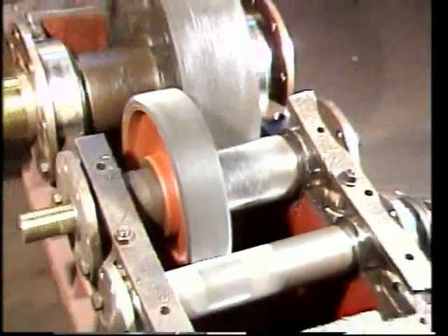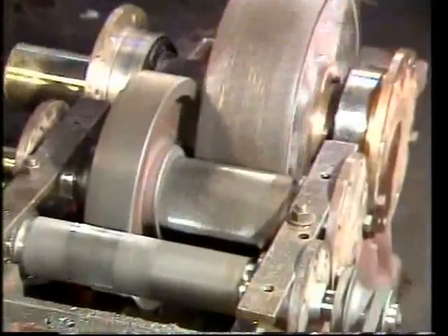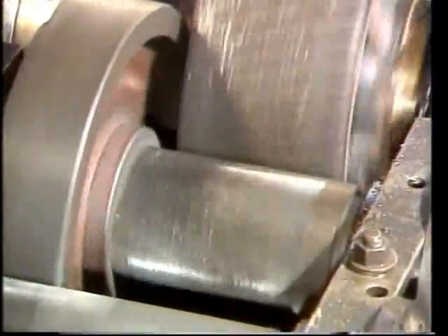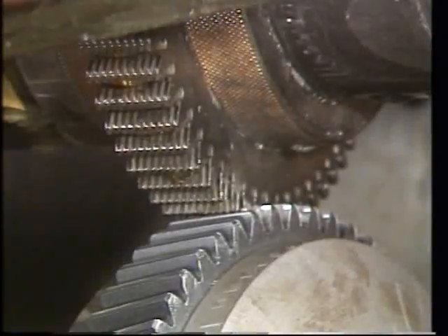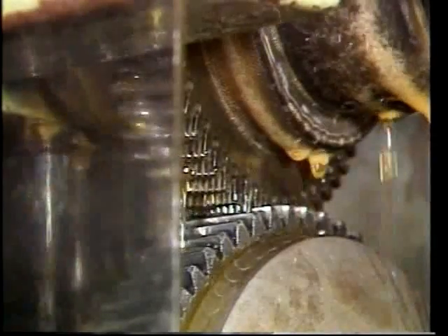The other common finishing process is lapping. It involves simply running the mating gears together with abrasive paste. It improves the surface finish by removing the scales. Gear shaving is a high finishing process in lesser time. The serrated edges of the finished tool shaves off the tiny flats on the surface.